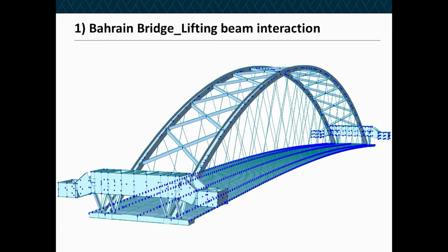Yeah. So we then change the support condition to out here, and the SPMT, Self-Propelled Modular Trailer Company, that were assisting us with this installation, again you'll see that equipment on the next slide, they gave us a set of forces that they said would be hydraulically controlled. Okay? And we were able to assign all of those loads to these support conditions outside the lifting frame, and then those forces would effectively be transferred through the frame and into the bridge, and we could complete our erection stress analysis and make sure that we had looked after the bridge in the best way possible.